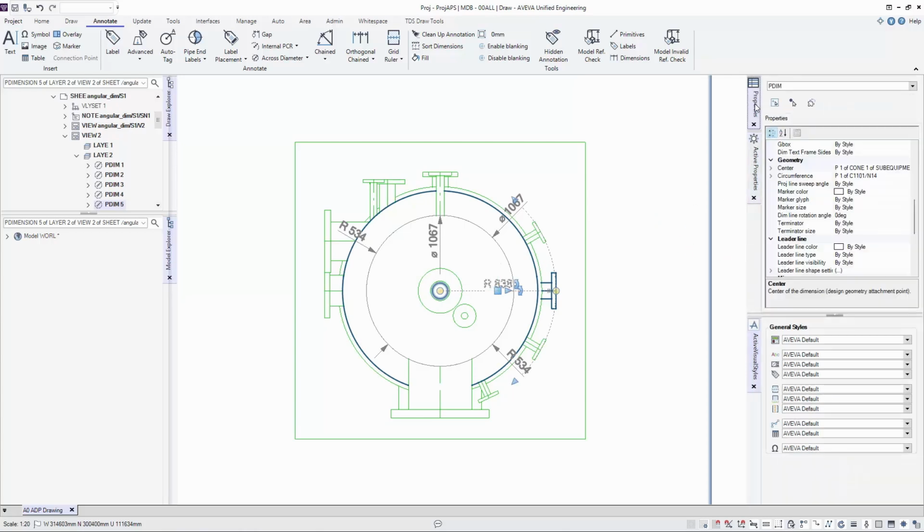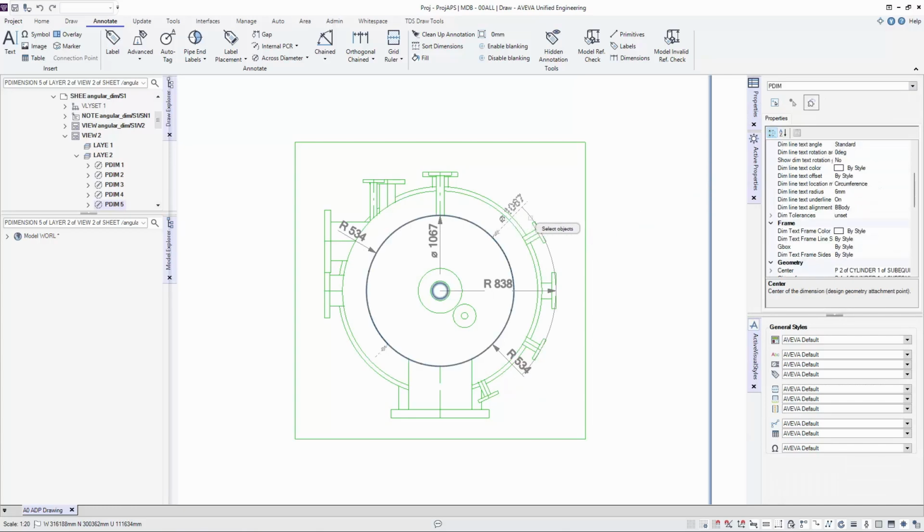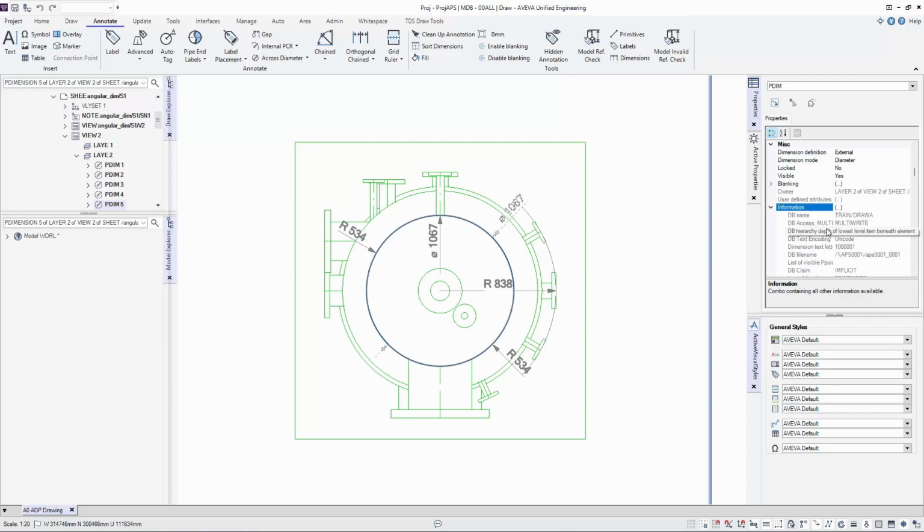We open the Properties pane to inspect the settings. The element type for a pitch circle dimension is PDIM. We change the visual style of the dimension. The list of properties can be quite long, so we set the display order to alphabetical instead of grouping by function. Since the list is in alphabetical order, the visual property appears near the end of the properties list. We change the visual style from the list, and the dimension updates immediately to reflect the new appearance.